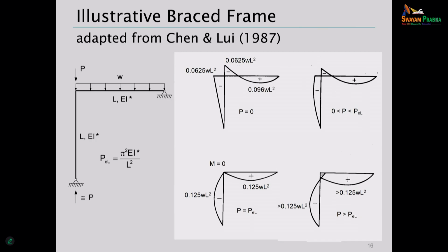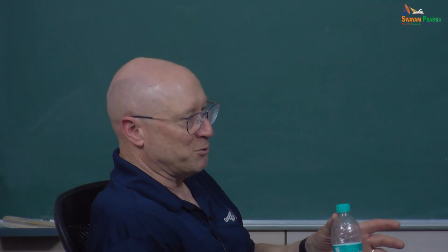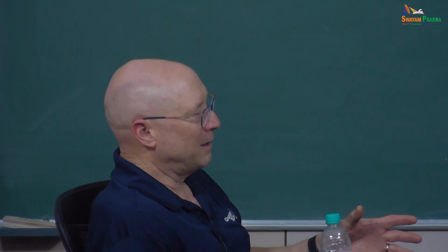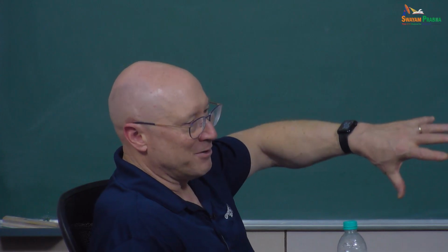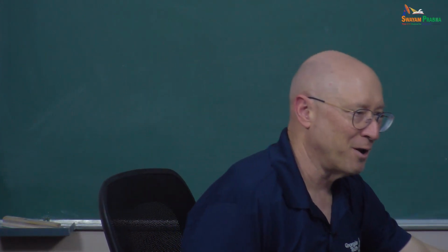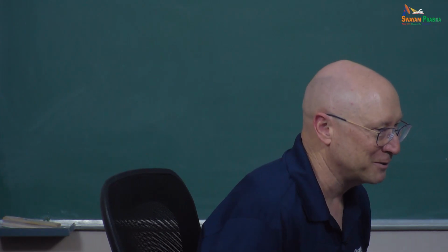Yeah, I think the difference from the case you're thinking of is this: if you do it with a spring, you're right, you won't get the 0. You should not exactly go to 0. But notice that here it's not a spring. It's a member with a uniformly distributed load. So we're starting out with a negative moment there at the knee because of that distributed loading on the beam. So that's a little bit different than the spring case.